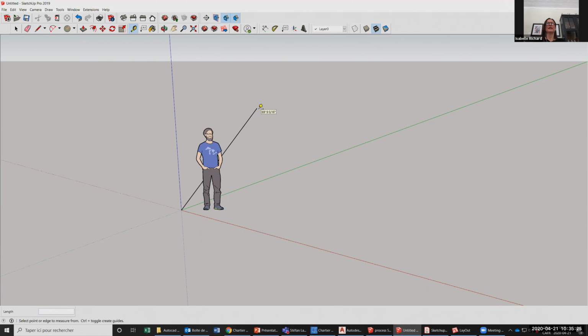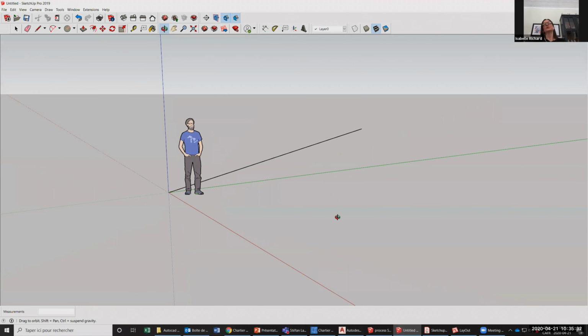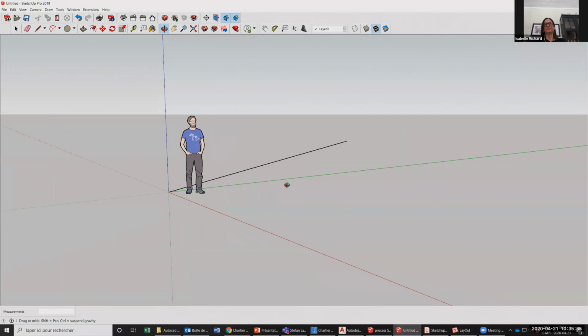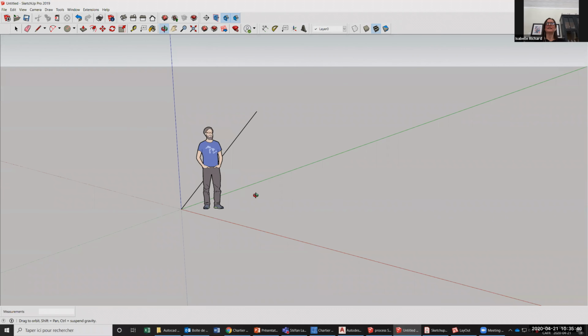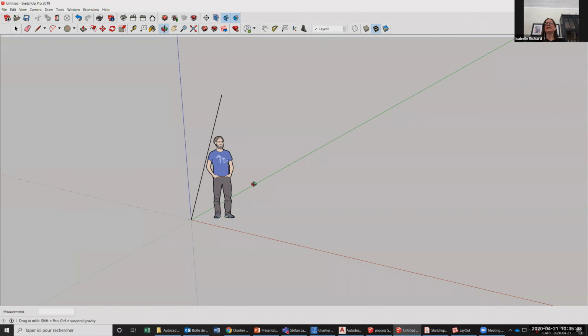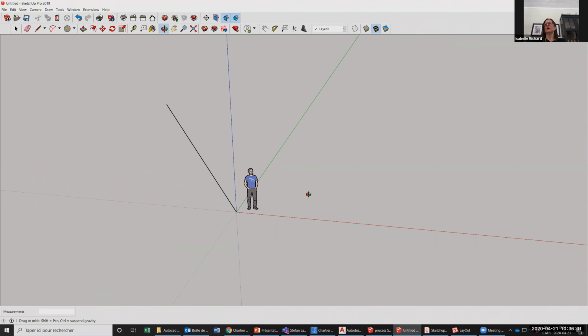So it gives you an idea of the measurement, but you don't see much of where you've drawn your line, right? So that brings me to one of the basic understandings of the drawing, which is that the axis lines are very, very important in SketchUp drawing. So you want to make sure you draw along the axes, mainly because we draw cabinets. So we draw something that is quite square, and you want to make sure it's right on plan.